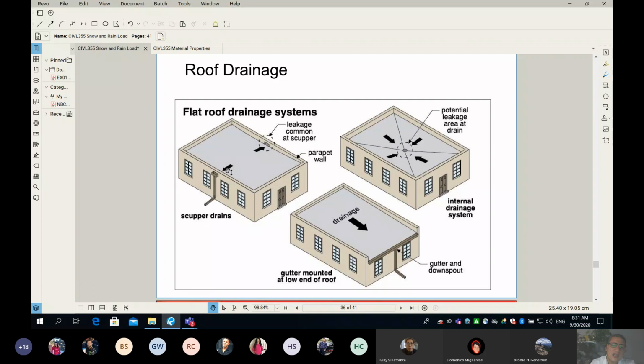The other way is this. In this building, we also have to slope our roof, and then we provide a drain in the parapet. You can see there is a little parapet, and if we don't allow water to drain off, the roof will be loaded. So we make a box, a hole inside the parapet, and this hole is called a scupper. The scupper will take the water downwards to a downward spout, and here we go, we get rid of the water.